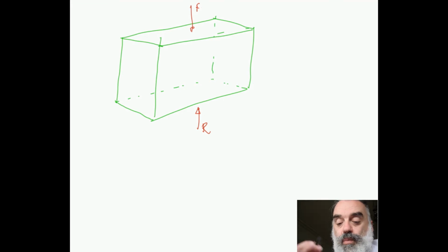And for equilibrium, we can generate an equation, and we can say that the sum of all the actions in the vertical direction have to add up to 0. In order that we can consider other directions, we need to come up with some system of coordinates. And for the purposes of this exercise, we will come up with a system of coordinates which you may have come across if you've studied maths.